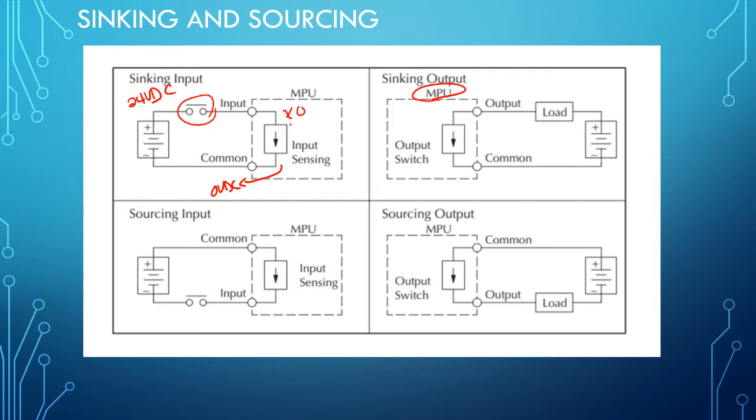It doesn't mean that I'm running a 24 volts DC cable straight to 0 volts DC. That is known as a short circuit, and that could definitely damage any power source. So if I do that, I'm damaging my power supply. Notice that they have a little symbol here. That symbol is an electronic device that doesn't permit this to happen. So just take that into consideration.